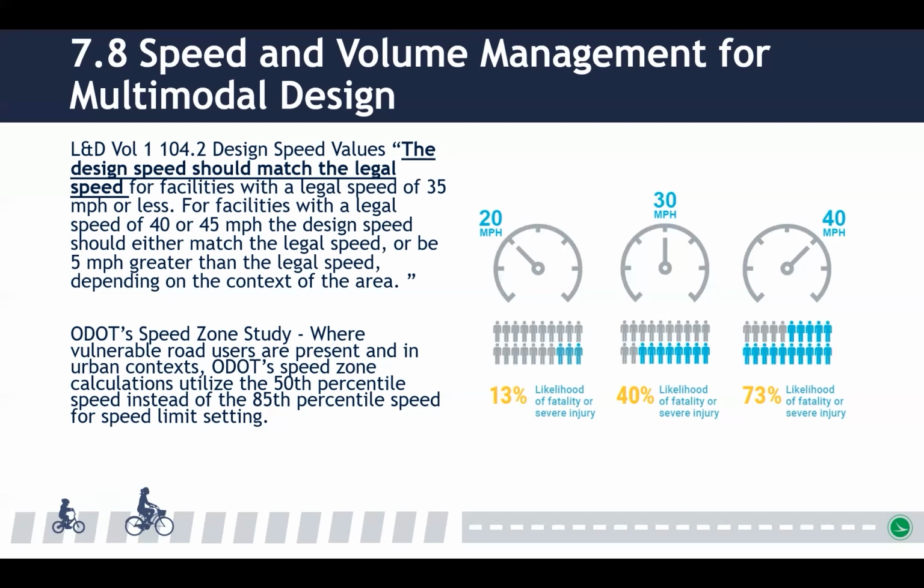Traffic calming devices help to manage motor vehicle operating speeds and volumes by introducing changes to the roadway cross-section or horizontal deflection, pavement elevation or vertical deflection, reductions in roadway width, alterations to typical motor vehicle travel patterns, or a combination of these techniques. By managing speeds, reinforcing target design speeds, and managing volumes, traffic calming increases the comfort of a shared operating environment and minimizes conflicts between users.